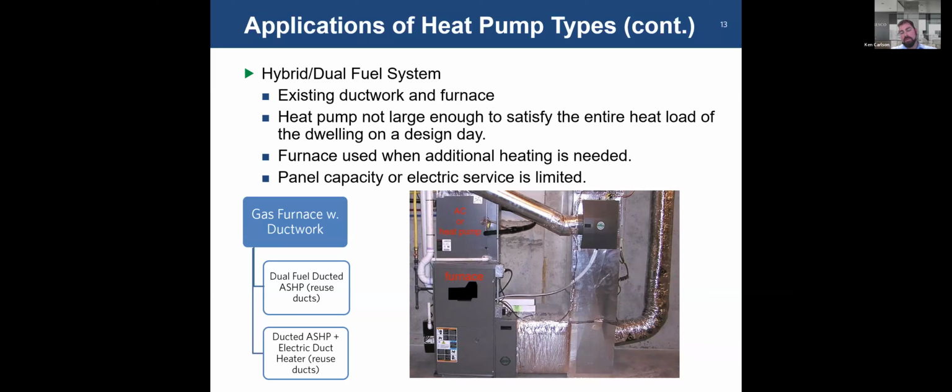You want to try to reduce your operating costs. You could potentially utilize a heat pump in the existing configuration, using a new furnace with a new heat pump in lieu of that AC unit. So you could still utilize all the existing ductwork. You could use the existing furnace if it's still in good shape, or you would replace everything as a package. More often than not, that's the way that you would go. Everything would be matching at that point.